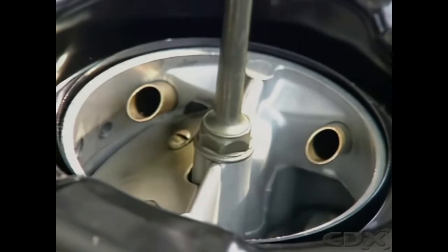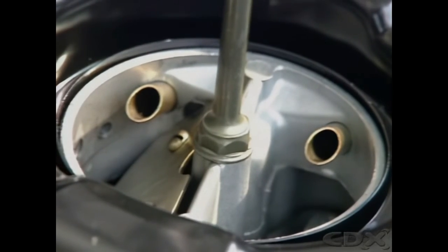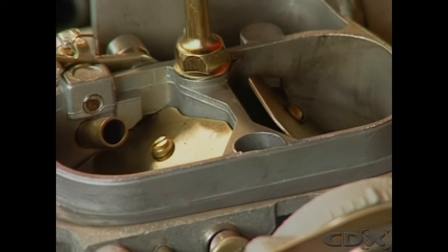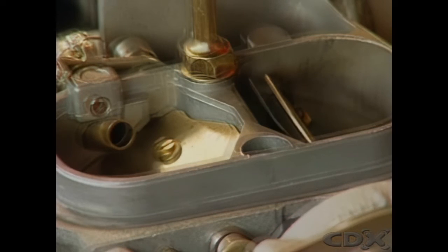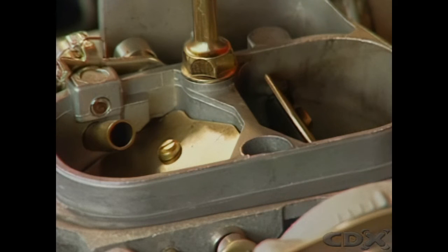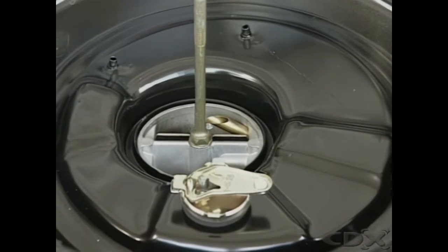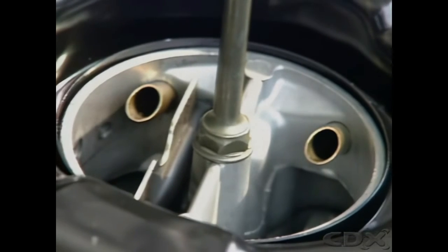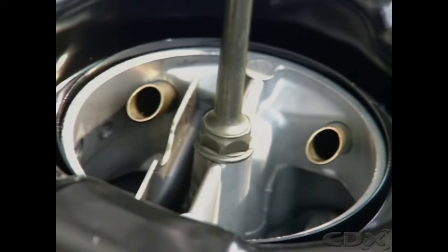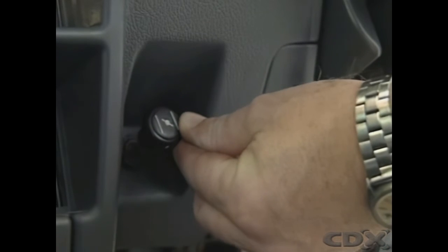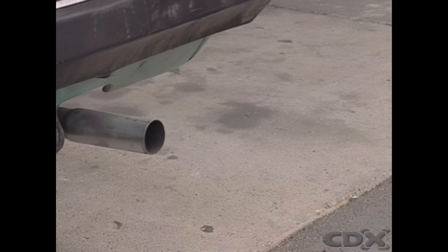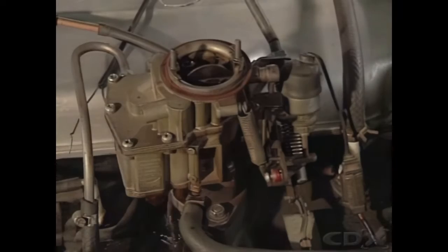The choke can be controlled manually by a cable that operates the valve. Most are controlled automatically, so that the valve is closed when the engine is cold and opens progressively as the engine warms up. When the engine is warm, the fuel drawn into the manifold during starting vaporizes readily, and the engine can be started without the aid of a choke. The choke should operate as briefly as possible. Overusing it produces rich mixtures that cause exhaust pollution and increase fuel consumption.